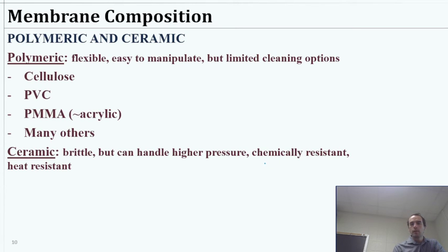And this is a project that a lab mate of mine back in grad school as a master's student was working on. It was treating water that was used to capture some of the pollutants from a coal-fired power plant. So you take this flue gas and do some water stripping to get out a lot of the contaminants, and then you need to filter the water, but it's like 70 degrees Celsius. So it's very hot, would probably melt most polymers or cause problems, but you could use a ceramic membrane, so that's kind of what he was looking at. And then you have an interesting advantage there because hot water is less viscous, so you get better permeability. So it's kind of a neat project.